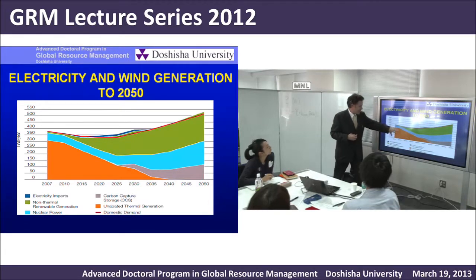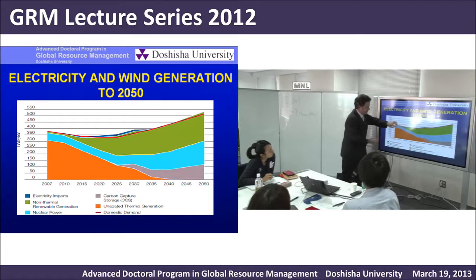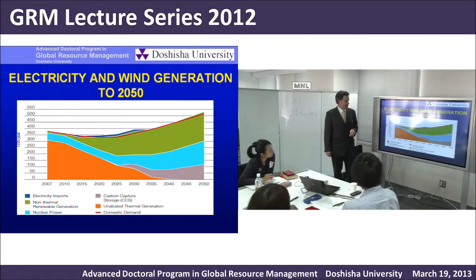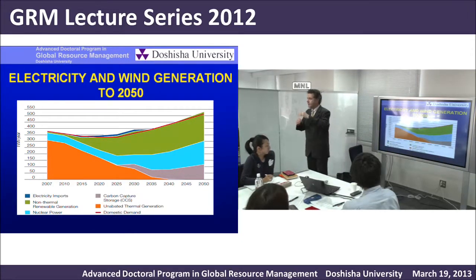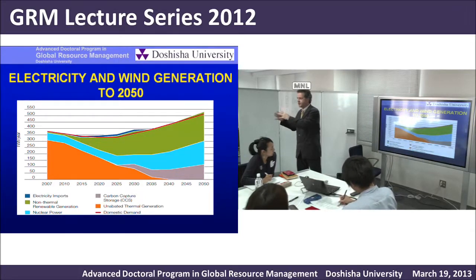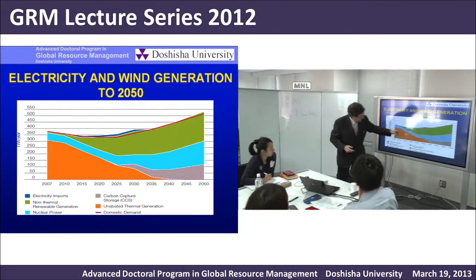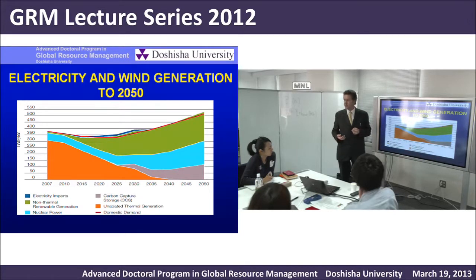But now, to 2020, we need to reduce conventional generation. How do we do that initially? We increase the renewables, and wind is going to be so big in this. So our little triangle growing there, our wedge through to 2025, is green. We've still got unabated generation, a lot of wind, and we're still keeping an element of nuclear. We can't go fully nuclear, because if we want wind, we can't have just wind and nuclear, because we can't change the nuclear output. So we need the orange stuff for the controllability, the variability, the operational reserve.